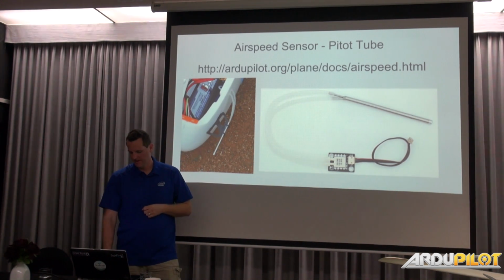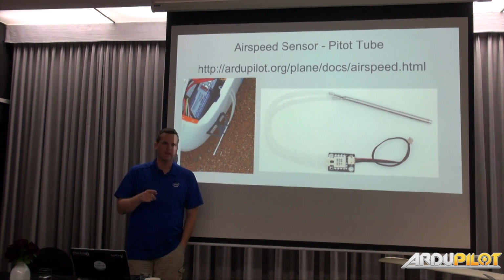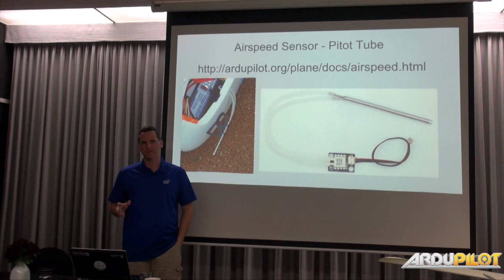Yeah, and it is angle dependent, so you can bank in flight and all of a sudden you have a massive airspeed reading and come back and lose it. So they're light sensitive, cover those up. Along with the pressure sensors, all the barometers, the family of sensors is light sensitive.